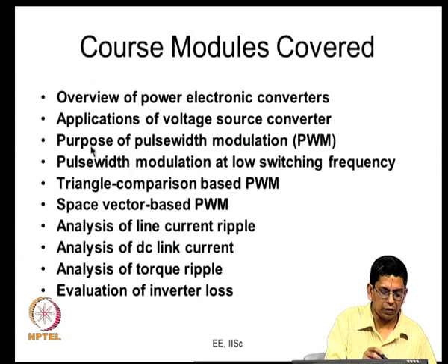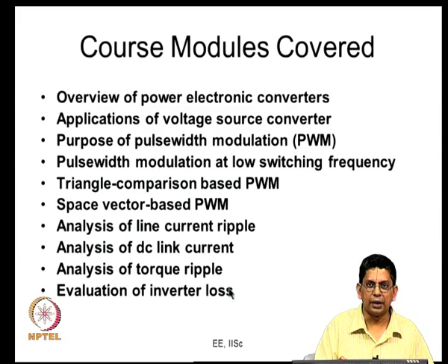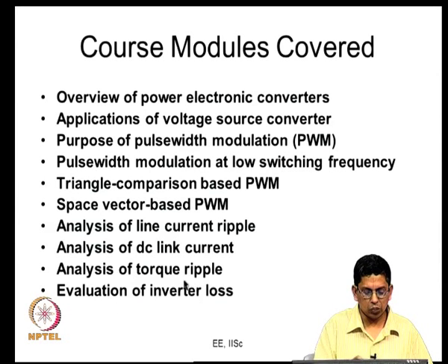Up to this part we considered the inverter to be ideal, with no non-idealities considered. Here we started looking at these non-idealities. Firstly, the non-idealities in the devices. So, there is forward loss, the drop, and therefore conduction loss, and there are switching losses. We spent about 3 lectures on how you would calculate these losses.